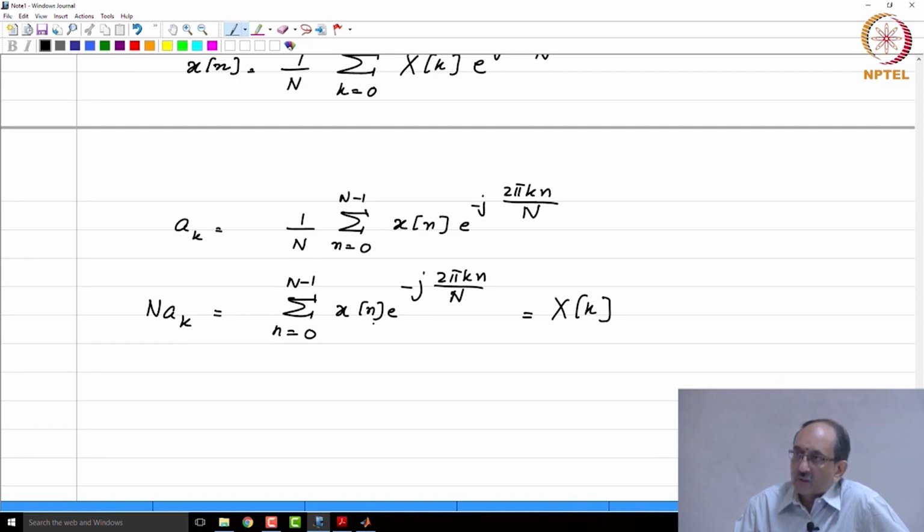Continuous time Fourier series: the independent variable is continuous, no good for machine representation. The Fourier series coefficients are infinite in number, even though they are discrete, no good. Continuous time Fourier transform: both the signal and the transform are in general infinite in duration. Not only that, the independent variable is continuous. DTFT is nothing but CTFS in disguise, again no good for machine representation.